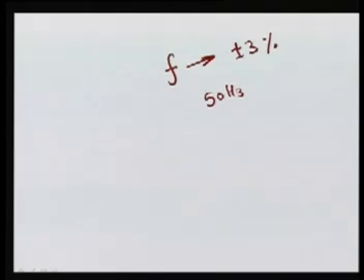In Asian and European countries we operate our power system at 50 Hertz, whereas the USA and Canada operate at 60 Hertz. So if your frequency of operation is 50 Hertz, then plus minus 3% means you must operate your power system from 48.5 Hertz to 51.5 Hertz.